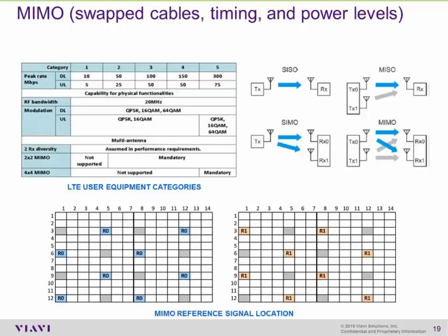Now, I do want to share something with you. Example, of Alcatel-Lucent. In 3GPP specifications, remember we talked about the primary, secondary sync? These are what's used to identify a sector. And 3GPP specifications allows or requires that it be on at least the first transmit, but it's optional as to whether or not they put on the second transmit.